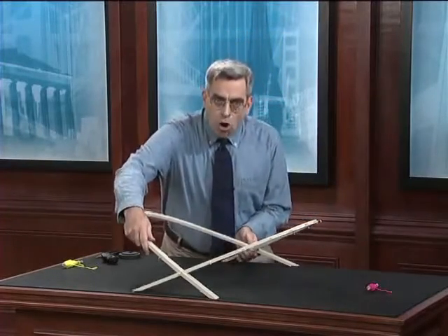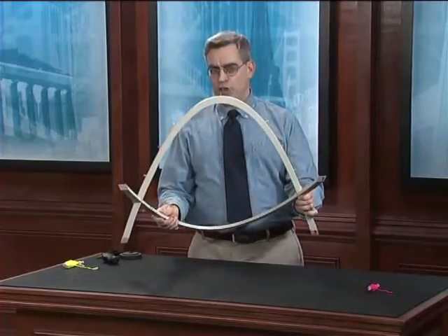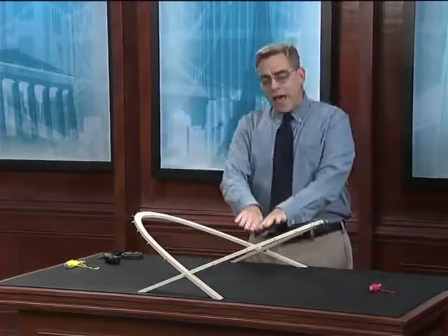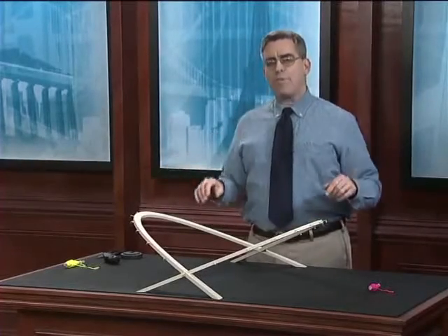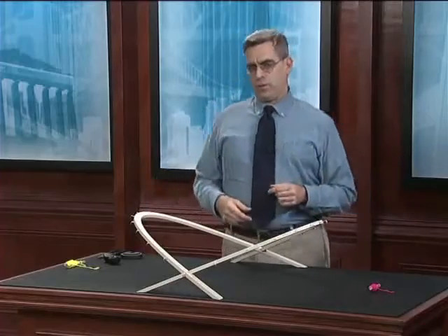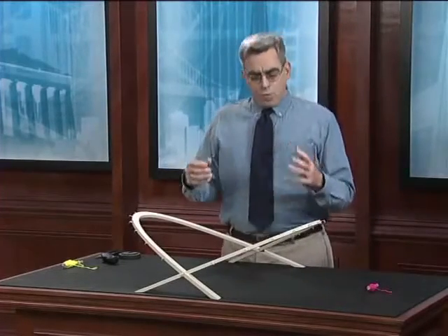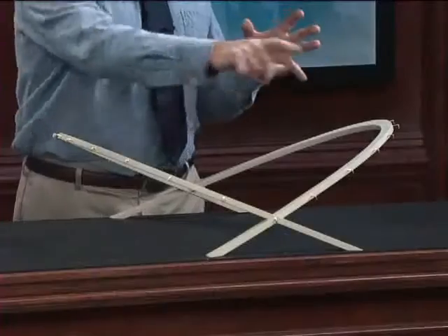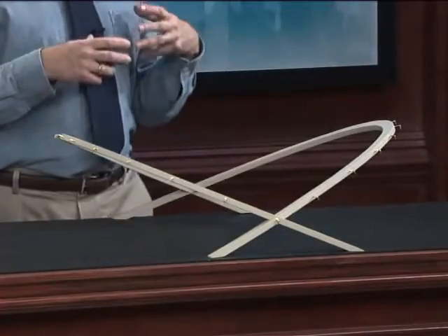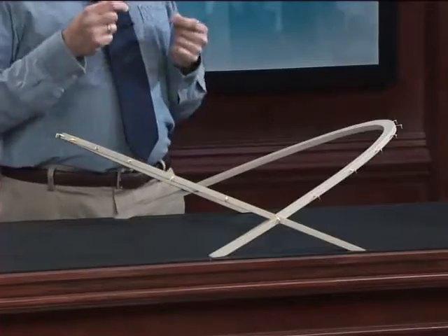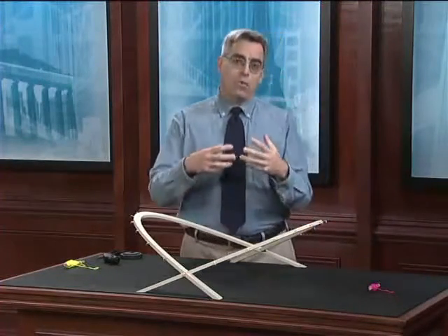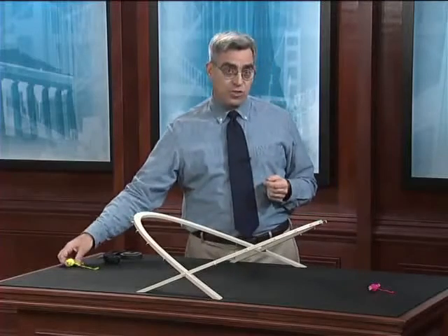The arches are each parabolic in shape, but in the actual structure, as you can see here, they're inclined on a sharp angle in opposite directions, intersecting about 26 feet above the ground. The roof then is suspended from these two intersecting arches, and it's developed in the form of two sets of intersecting steel cables. I'd like to add to our model by adding representations of those two sets of steel cables.